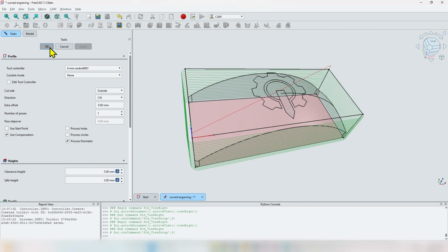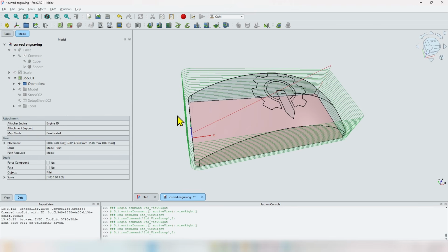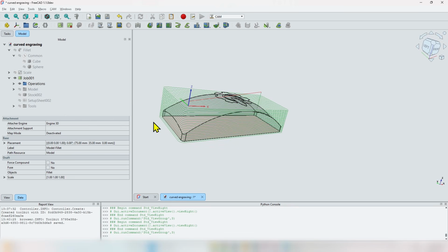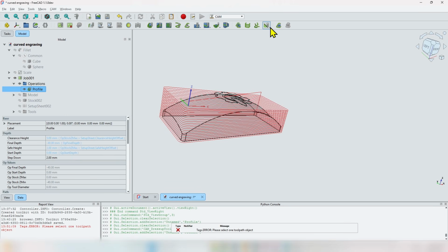Let's close the profile operation and set the final thing before moving on to Universal G-Code Sender, to the machine, setting everything and starting to mill this operation. And that thing is adding holding tags, so the piece of material will be held securely in place for the other two operations that we still have to mill after this one. To add the holding tags, open the operations group, select the profile operation, go to this button, click on the little arrow next to it.